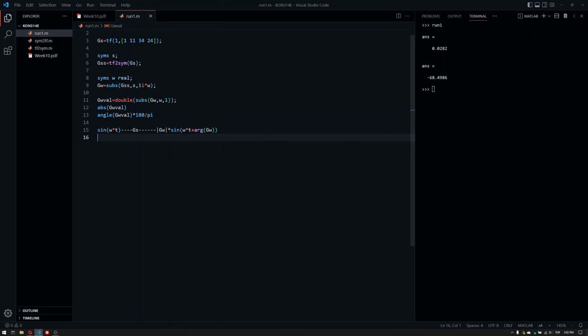Or you can comment on your system's behavior when you examine the phase and gain plot versus frequency, so you can get the feeling of how your system will behave at low, mid-range, and high frequencies. Up to this point, most of the time, we have looked at step type inputs, maybe ramp inputs to a certain degree, but those are kind of slow signals, but it's not quite correct to call them low frequency signals, because the sharp edge of the rising or falling edge of a step input has some high frequency components in it.